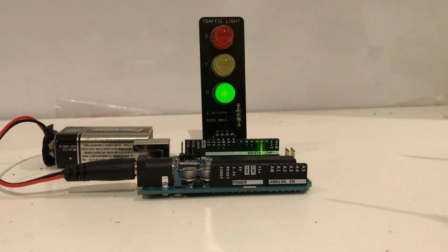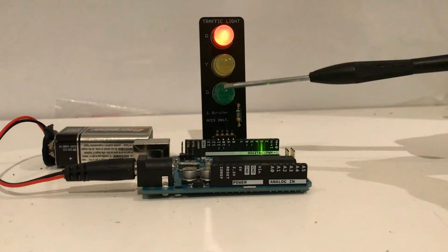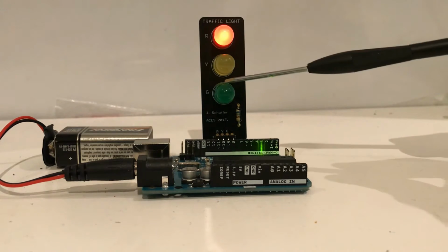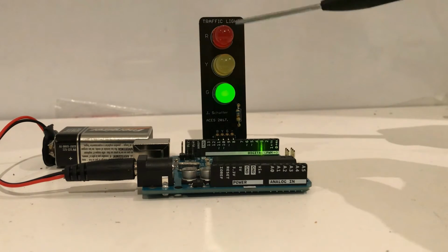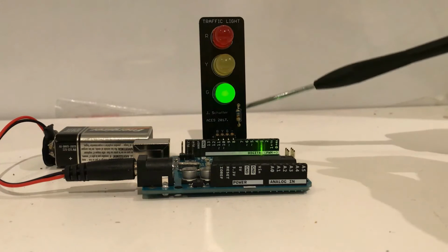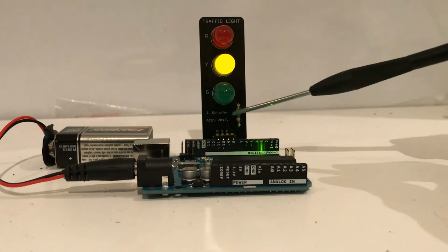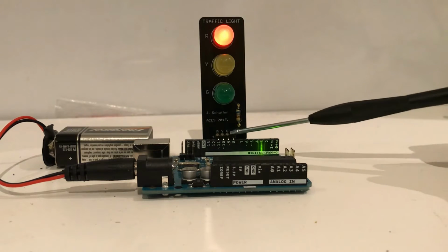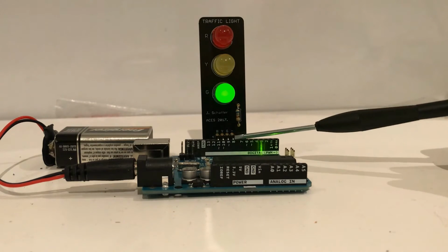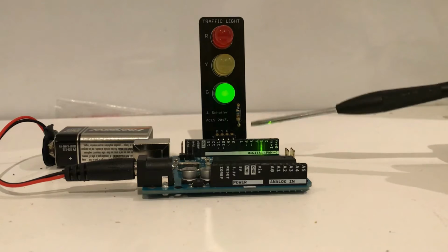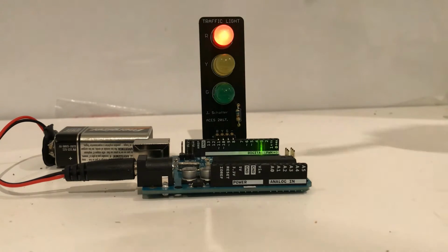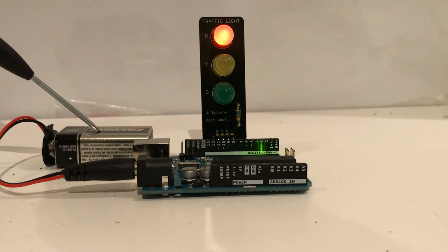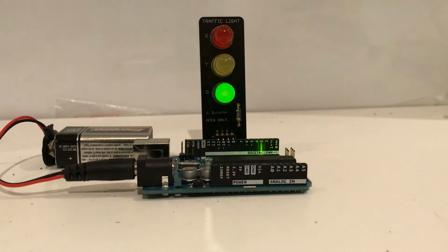This project features an Arduino Uno, three 10mm LEDs, one green, one yellow, and one red, all soldered into a traffic light PCB designed by Jay Schaffer, one 670 ohm resistor, four male-to-male right-angled header pins, which lets the PCB connect to either an Arduino or breadboard, and one power source, which in this case is a 9-volt battery.